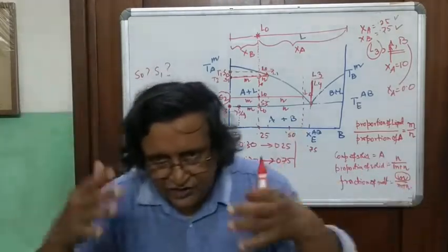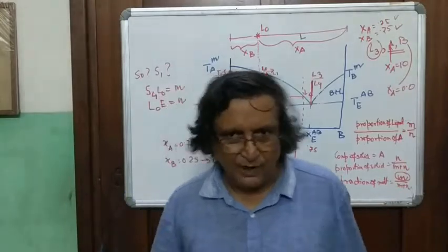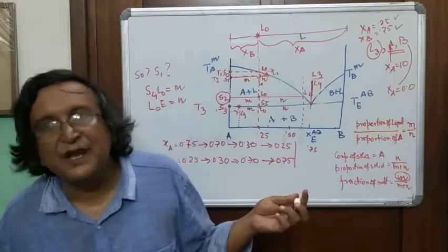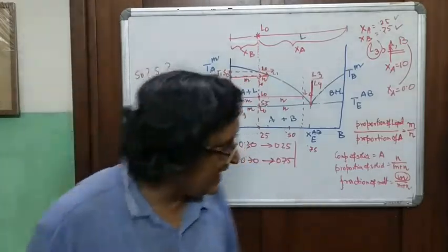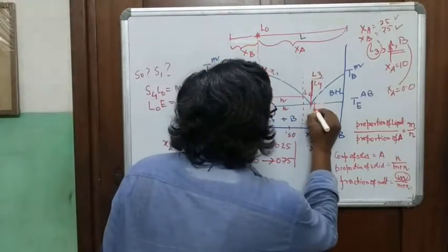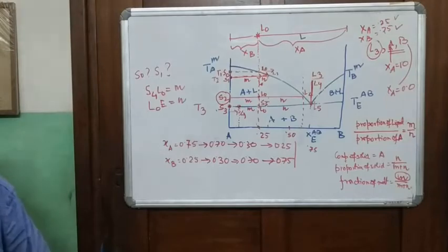But if you go on taking away 2 girls and 2 boys in steps, finally you will have no one in the class. That's where your melt composition becomes 0. It's exactly the same situation, eutectic. So when you have S5, your L5 is still here at the eutectic. It has not left the eutectic.